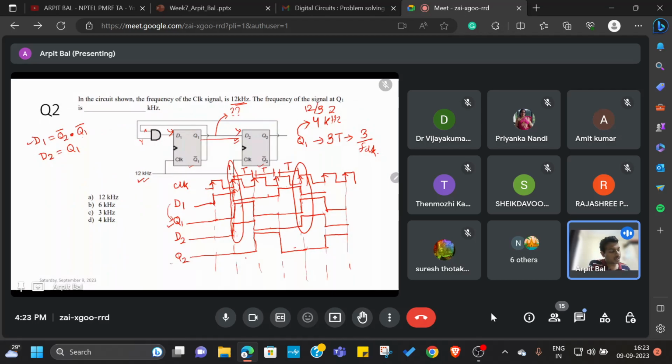In the next question, what I have seen is some people get confused with which input is going to get updated when. One thing that you need to remember is, if it is a combinational circuit, the moment the input to that combinational circuit changes, the output will also change at that moment itself. It will not wait for the clock to come. If it is a sequential circuit, then based on the arrival of the clock pulse or based on the enable signal, it will change its state. These 2 points are quite important, so please try to remember them.